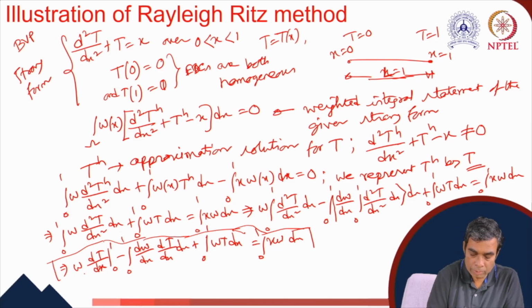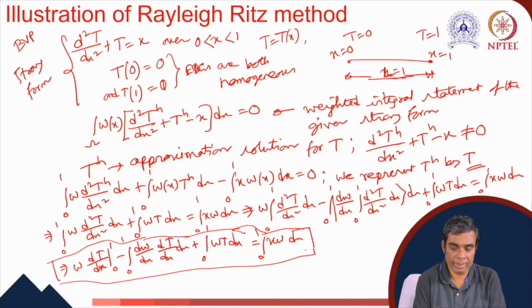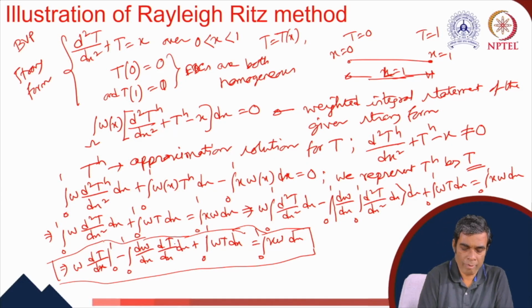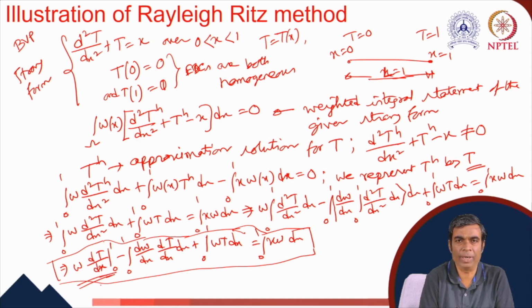If we look at this weak form, then we see that here the governing equation was of second order. So for this, we can maximum perform only one integration. We have performed one time integration. Now it has reduced the order of the equation. It has come to a first order equation with dT/dx as the first order term. In this expression, the first term on the left hand side is representing the natural boundary condition term.